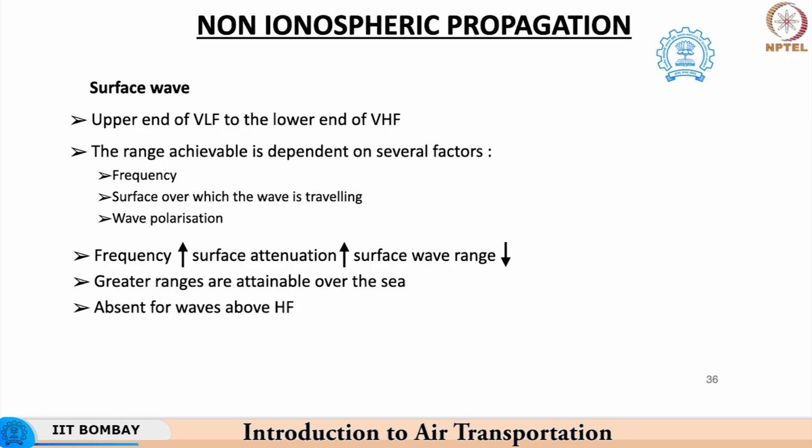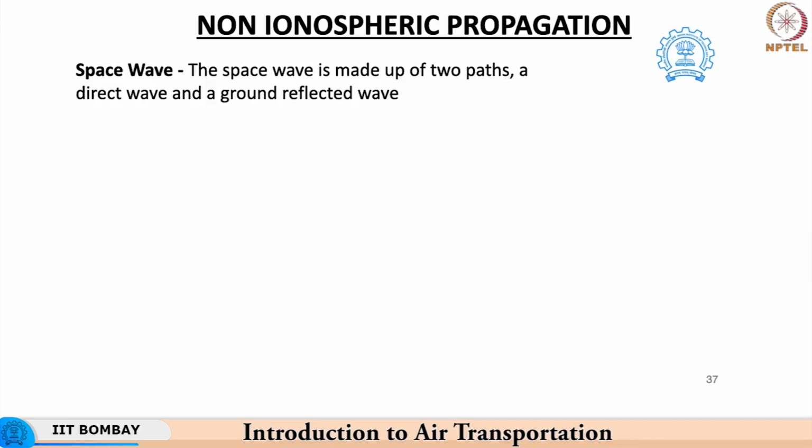On the other hand, if the communication happens over an oceanic region wherein the surface is smoother, the range of the communication is increased drastically, whereas if the frequency is very high, such a propagation path will not be possible and will hence be absent for all frequencies that operate above high frequency.